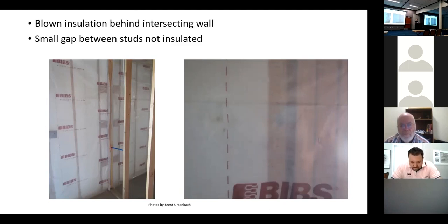We put in an HVAC system, and the HVAC guy says I'm going to draw my return air under the door, but the door fits tight to the carpet. So the HVAC system runs, and what does it do in the bedrooms? It pressurizes the bedrooms. So any moisture that we have in our air, we're shoving it into our walls, aren't we? Because we pressurize the room.